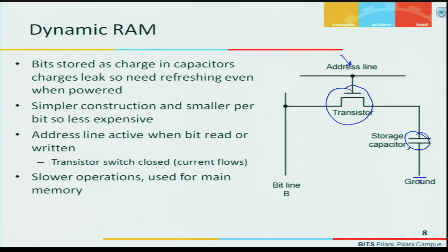In case of the static RAM, as long as the power supply is there, the voltage level remains the same or constant. So, you do not require any refresh circuit there, but here it does not remain constant due to this capacitor charge decay problem. So, we need a refresh circuit such that the charge can be maintained at that level. In that sense it is called dynamic.